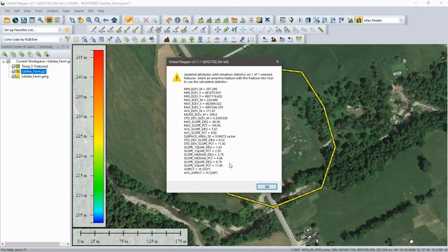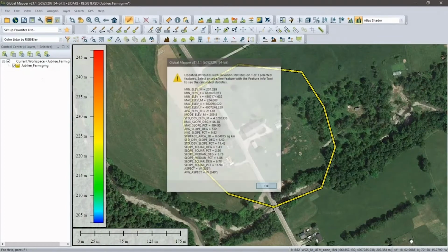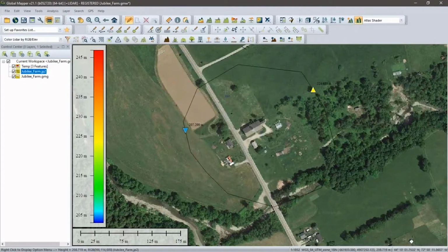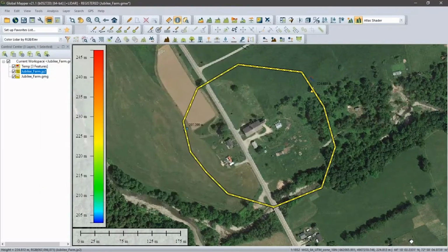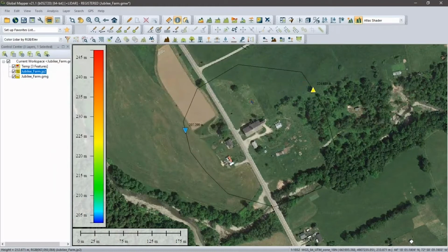into the air. That information, all of this detailed information, is also accessed within this polygon now. If I select the info tool and select it, again, we have all of this attribute data now associated with our project area. A quick report of the terrain characteristics, as well as, as you see as a byproduct, we know the low point and the high point. So we've got a snapshot of what the natural environment or the terrain characteristics are going to be in that area.